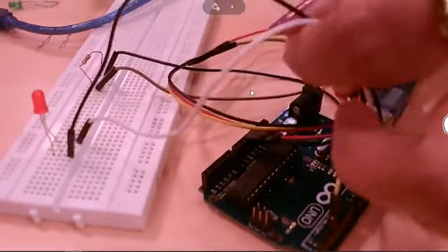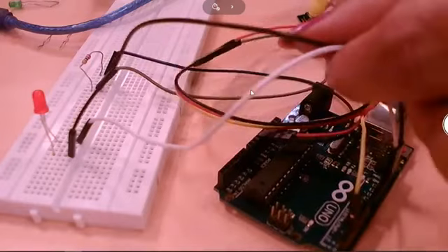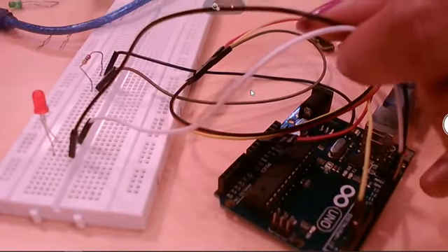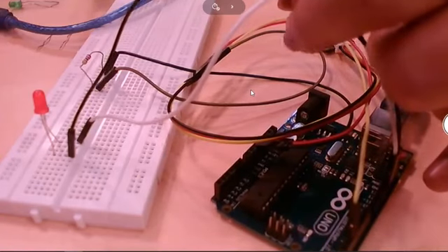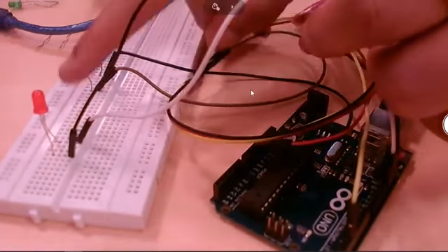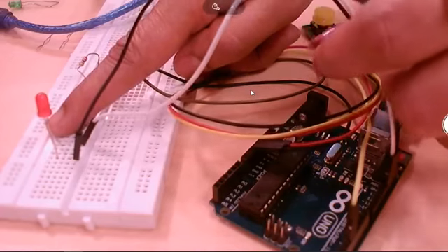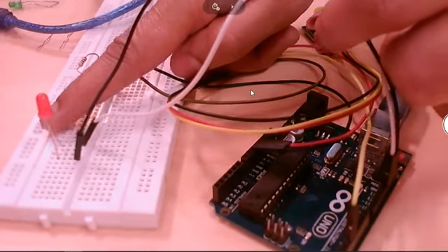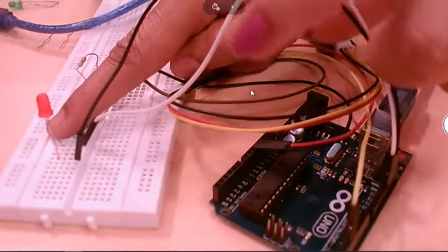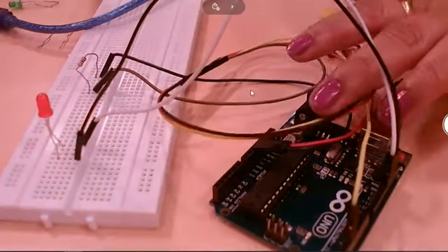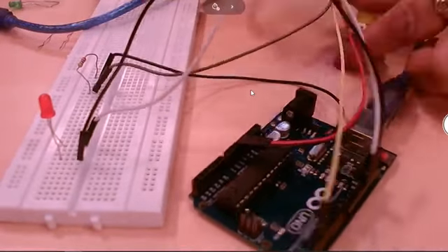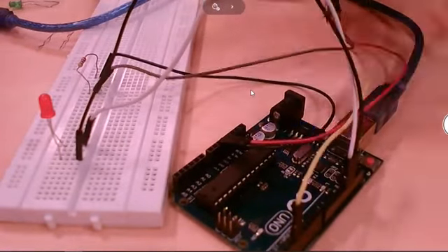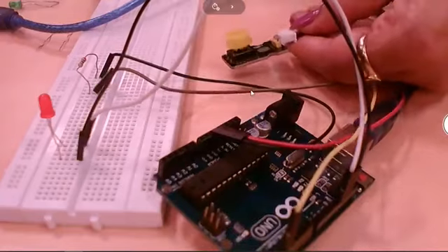Now since I am connecting this LED to pin number 13 on the digital section here, and since that inbuilt pin 13 has a series resistor, I am not connecting any additional resistor over here. So that's fine. The current through that LED will be controlled by the inbuilt resistor from the Arduino board. Now to see the connection of this button, let me highlight it properly here.